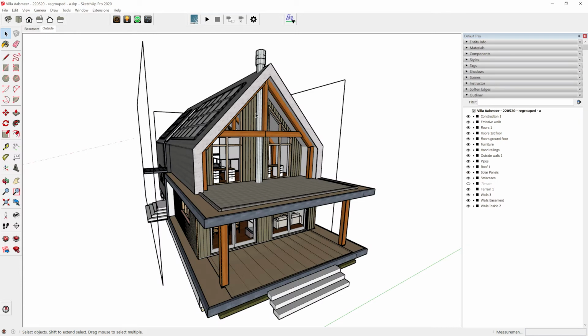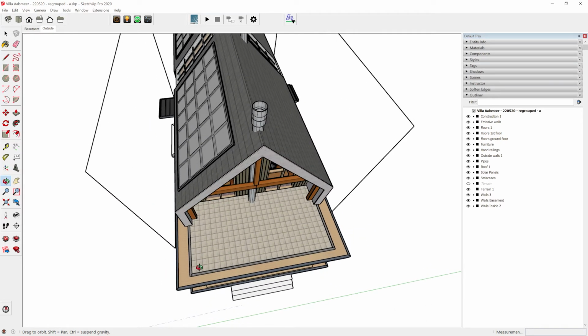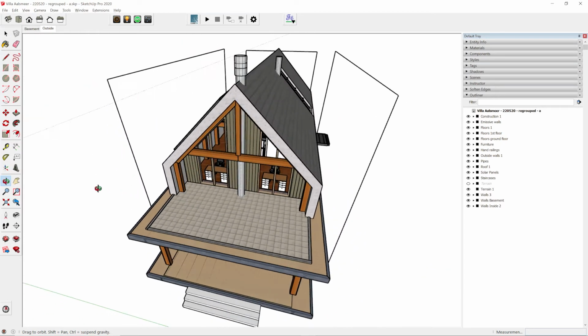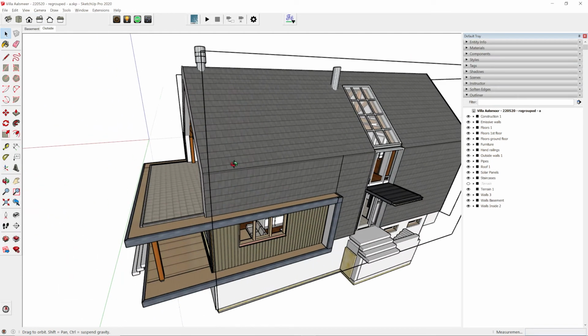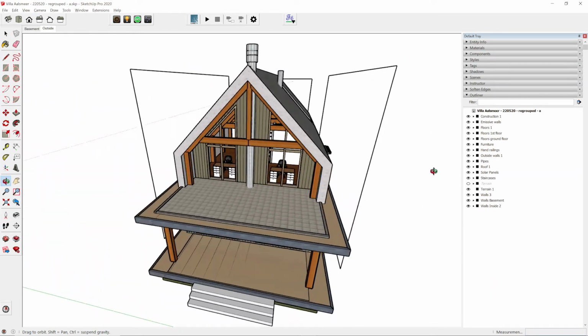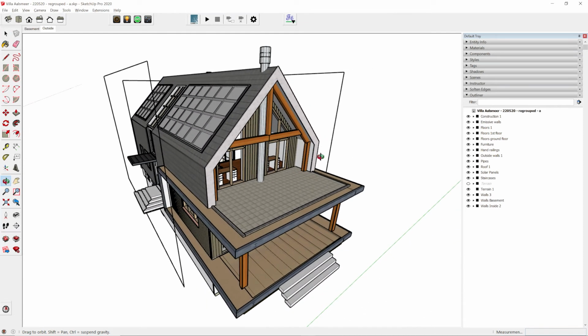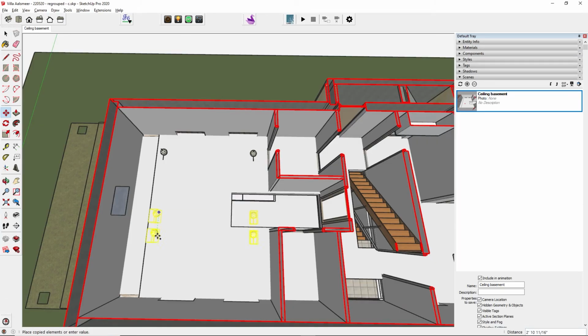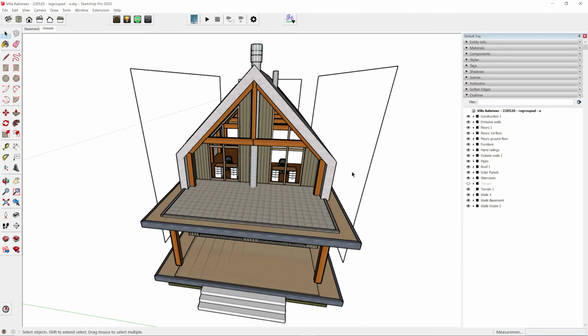There are 2 ways to improve the lighting and shadowing in SketchUp so that you get a better result with the LightUp plugin. The first is to add emissive planes outside the building so that the light comes in through the windows. The second way is to add lights to the ceiling and walls on the inside of the building. Both methods have their pros and cons. First, we'll try the emissive planes method.